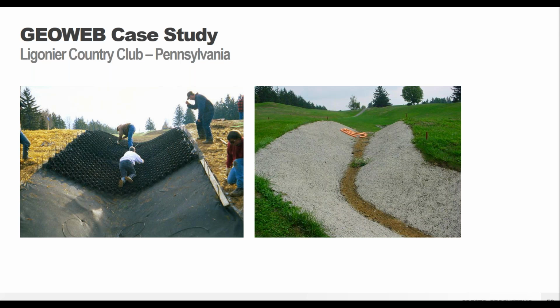And then you don't need additional formwork around it. You just start pouring the concrete directly into those panels. So that really can save a lot of time in installation. It makes it a little easier that you don't need to be confined to rigid formwork or rigid internal reinforcement. You've got flexibility. You can make it look a little more natural, go around curves a little nicer, that sort of thing.